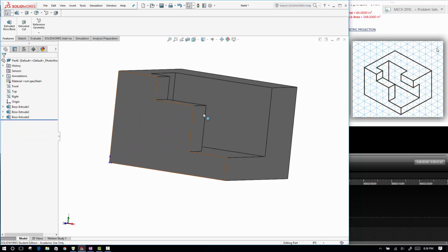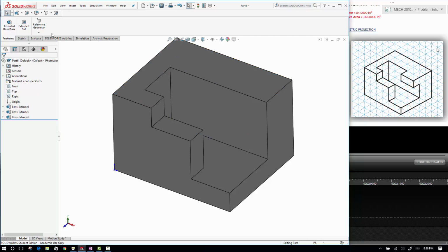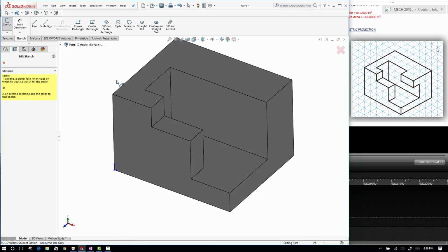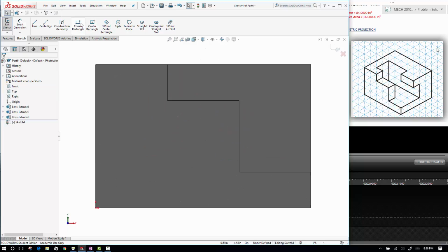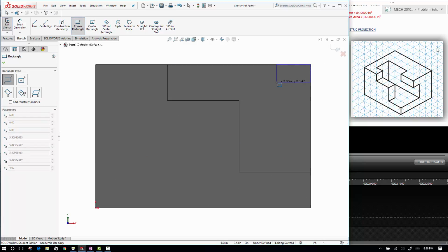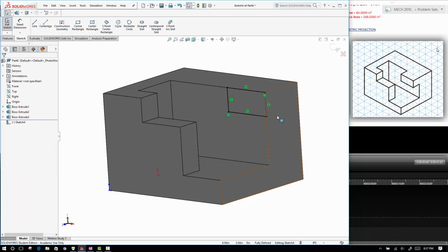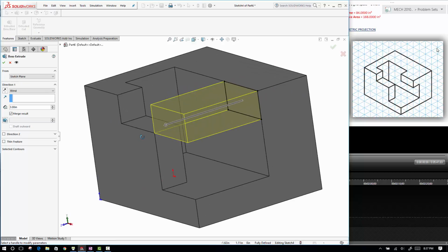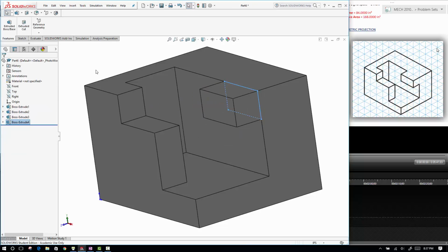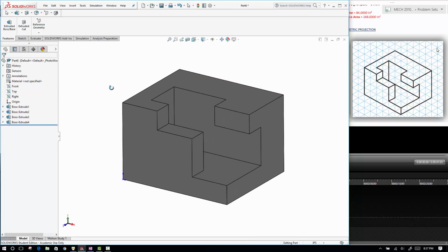And that's selected. And the last thing I need to do is make my rectangle on this surface. So I'll go Sketch, Sketch, select this, and I'll use my corner rectangle here. But because I'm in this view, I can actually select that vertex as well, even though they're fairly separated from each other, but that's going to give me a fully constrained sketch, and I need to come at a distance of 1. So I'll do an extruded boss here of a distance of not 3, but 1. And that again creates the part. So one's doing it subtractive and one doing it as an additive process.